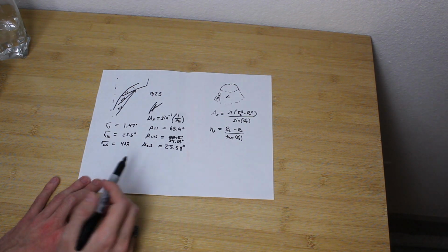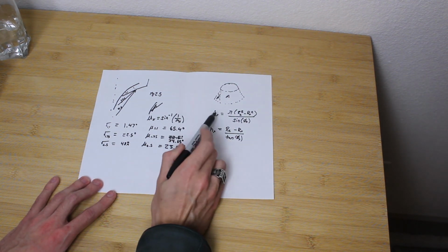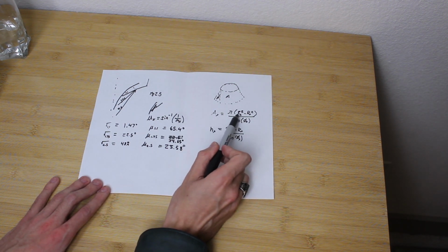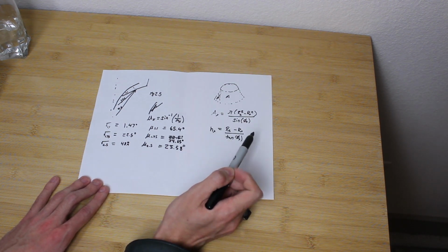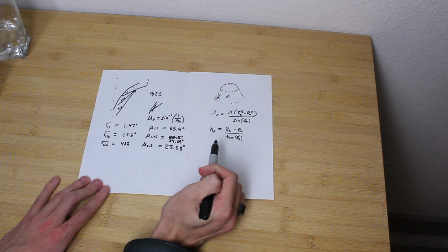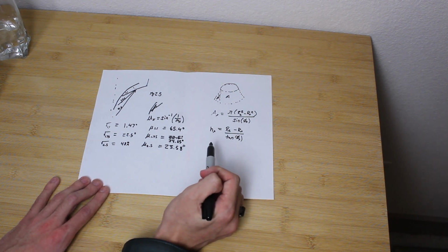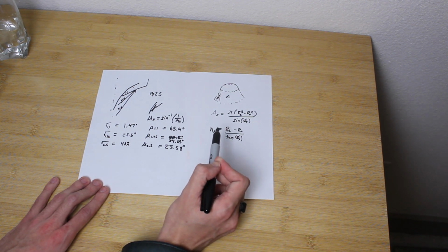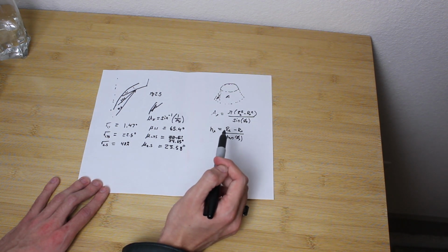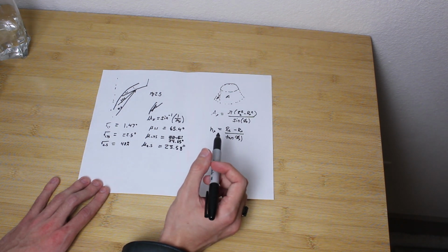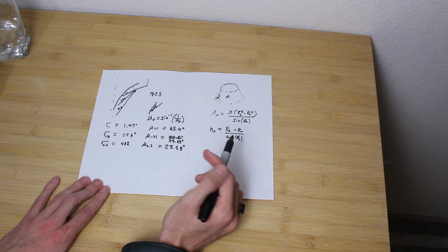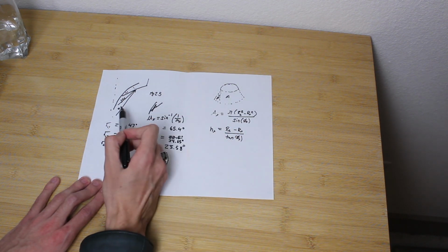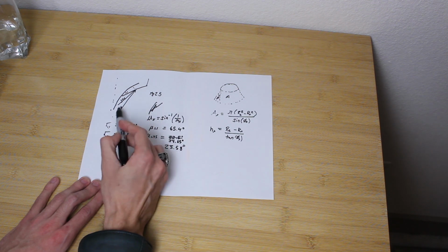Alright, so we're almost there. We know everything we need to know to solve for the contour of the spike, except we still have a floating relationship between the radius of the spike and the height of the spike, and we don't have a solution for that yet. There's a variety of ways we could do this, but aside from guessing and checking, the right way is to solve for the mass flux through the throat, which is also going to be equal to the mass flux through the frustum defined by this Mach 2.5 line here.